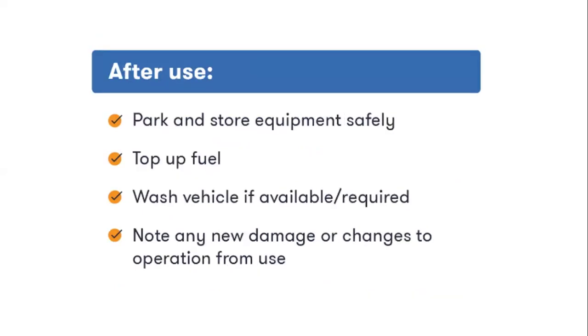And after using the machine, we have to store it in a safe area where it is protected from the external environment. Regular cleaning is also required. Why? Because the construction industry is one of the highly dust-generating industries. In some cases, this dust will enter the openings of the machines and tend to clog the fluid pipes and create problems. So routine cleaning is also required.